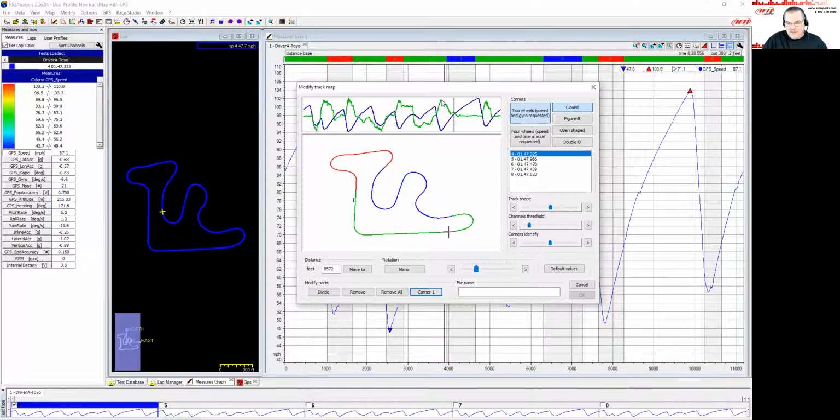The G-forces are up by the green line. It comes down, and then it starts to flat line. It looks like he held his hands a little bit and then went again. But right about where he ended the hard cornering part, maybe that's where I want it. And then we want to stay just a little off of the transitions either way. So I'm going to come up just a little bit more, and that's where I want to know how much time I spend in that little segment there.